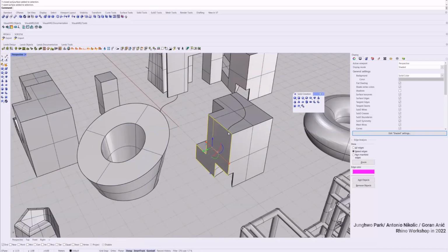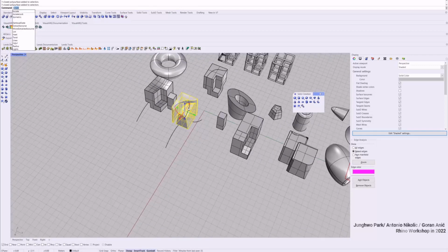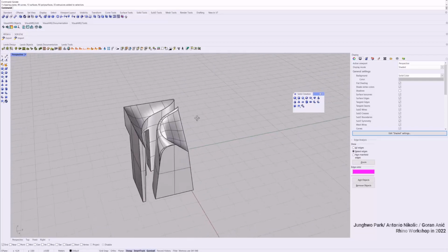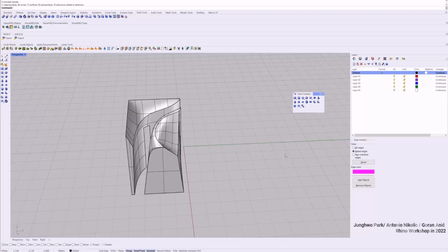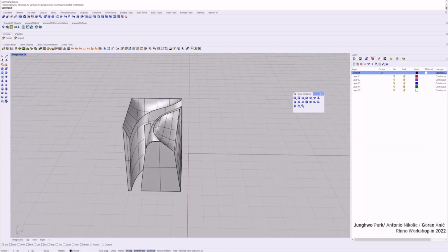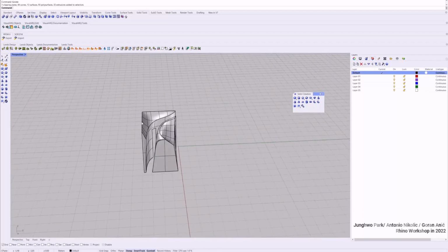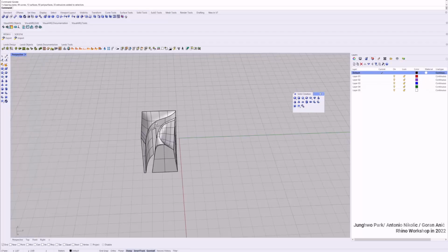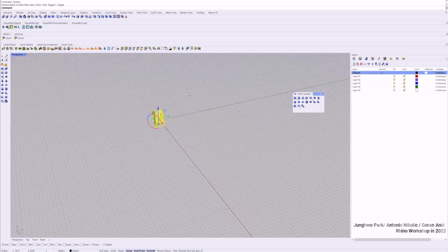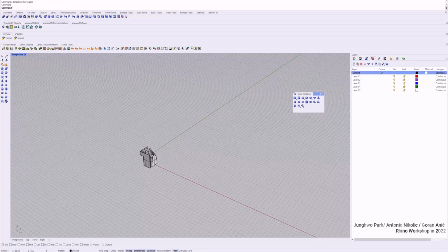I think that's pretty much all for solid objects. I'm gonna show you some other special tools. I'll isolate. Did I show Make2D already? No, as far as I remember. So what I'll do, I'll show you. Somehow I want to make a drawing of this, okay? And this is perspective, and I want to make this perspective view. If you press F6, you can see the camera of F6, no? Okay, it seems like not.